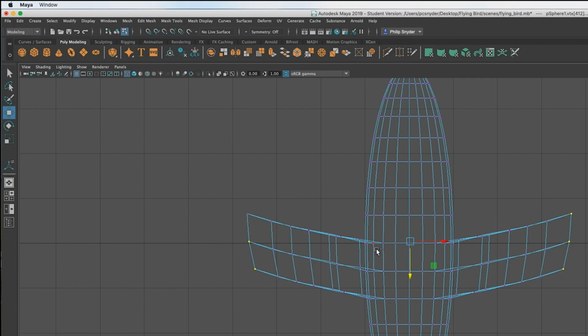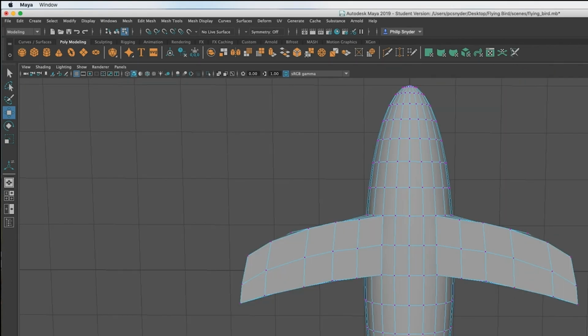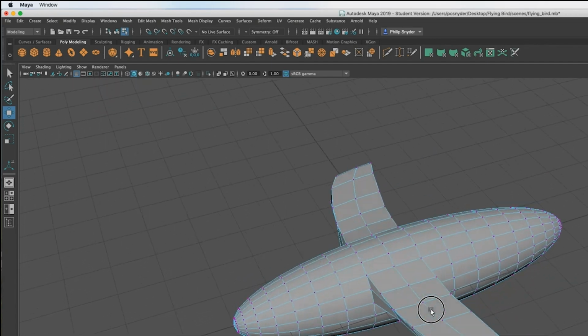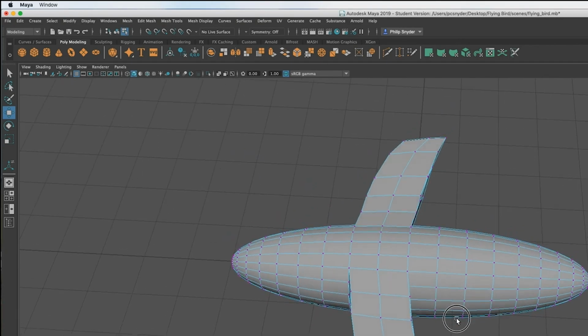Deselect the corners here, the back corner, and let's move these back a little bit to give a little more contour. And let's do these also so that they correspond. Shift, select box, and then move these back to match a little better. And so that's pretty good for now. Click off of it. Let's go back into the perspective mode. Okay, well that'll work for now. We'll do some more tweaking as we go along.